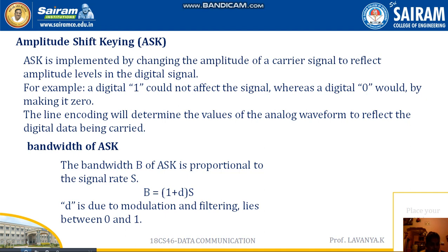A binary amplitude shift key basically works on the on-off key method, that we call the OOK method. The peak amplitude of one signal level is 0. The other is the same as the amplitude of the carrier frequency. The carrier frequency is also the same, but during that time only the amplitude is going to vary. How it is, I'll show in this diagram.